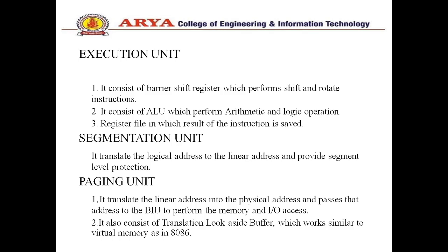Segmentation unit translates the logical address to the linear address and provides segment level protection. Next is the paging unit. Paging unit translates the linear address into the physical address and passes that address to the BIU to perform the memory and input output access. It also consists of a translation lookaside buffer, which works similar to virtual memory as in 8086.